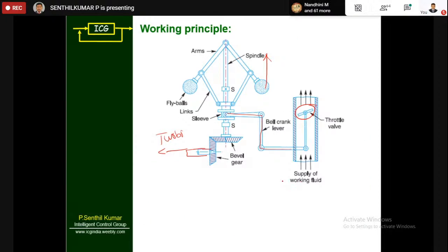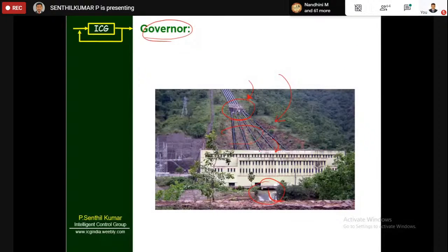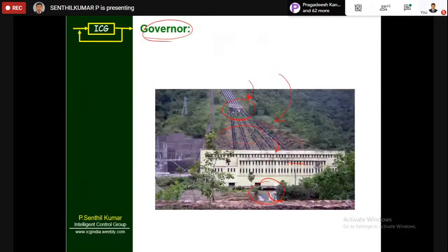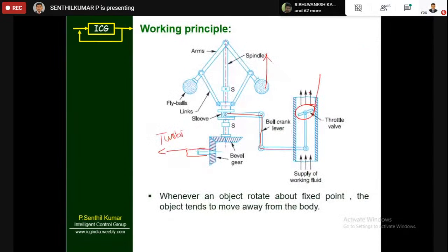Whatever water is coming through this jet, there is a bypass valve. So whatever water is coming through this jet will go through this side. Instead of hitting the turbine, it will go out. When this is closed, there is one more option here. It may hit the turbine. Okay, there is a turbine here, somewhere here. So whatever water comes through, it hits the turbine and will go out. This is the blocked throttle valve.